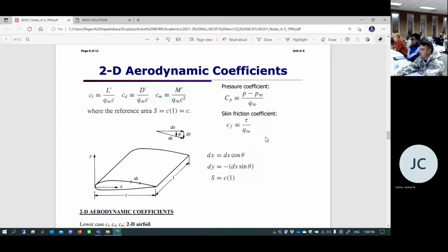Now, potential flow theory is coming up in Unit B. We are going to do full-blown mathematical analysis of the flow field, and we are going to choose this kind of path. One of them could be the upper surface, the other one the lower surface, but we can represent those as streamlines. We will understand later that the streamline that goes through the stagnation point is called the stagnation streamline, and it represents the surface of a body.